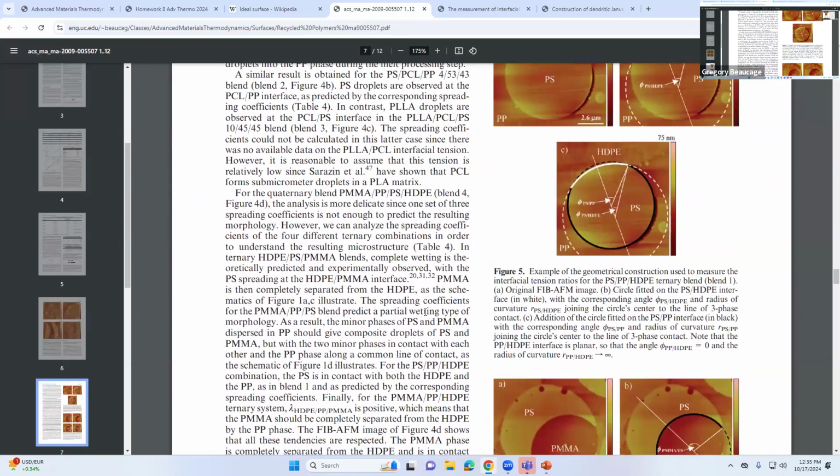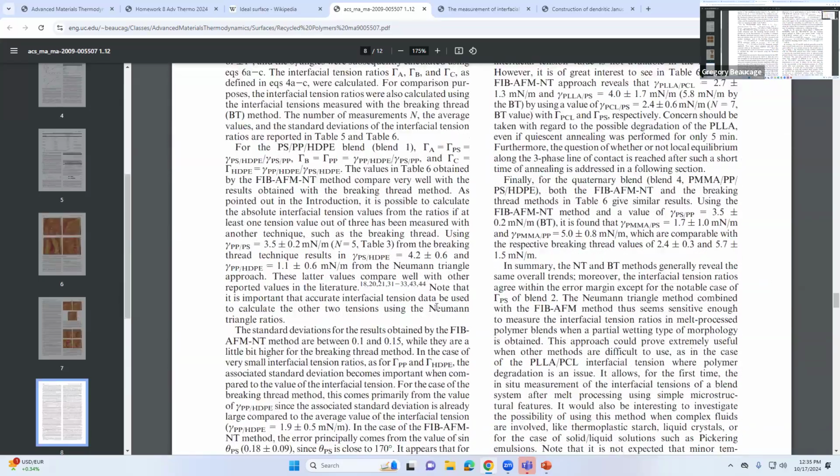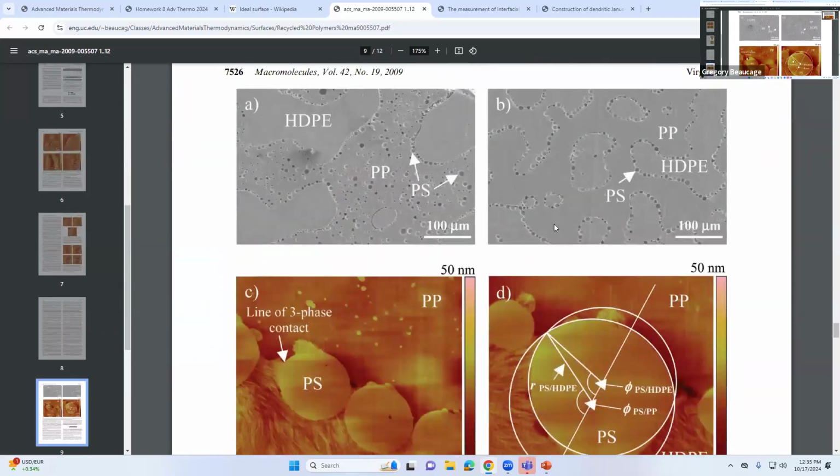And in fact, you can get something where you have little beads of one phase decorate the other phase. So here, polypropylene and high density polyethylene don't like each other. But the polystyrene has some kind of affinity for high density. So the polystyrene you put in, which is, like, a Scotch tape container, the plastic ones that are clear, is polystyrene. Right? So that's immiscible with everything, you know. So anyway, that's locating on the line.